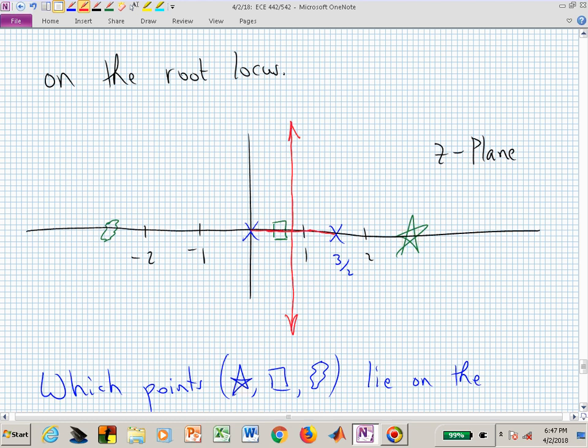So there's a gain k, and you can find that gain k when z is equal to 3/4 to get you right there. You crank up the gain a little bit more, and what happens? They go opposite directions, plus and minus 90 degrees, or well, 180 degrees away from each other. And if you crank up the gain too much, what's going to happen relative to the unit circle? It's going to go outside the unit circle. Do you see there's a range of k for stability with 2 poles and no finite zeros?